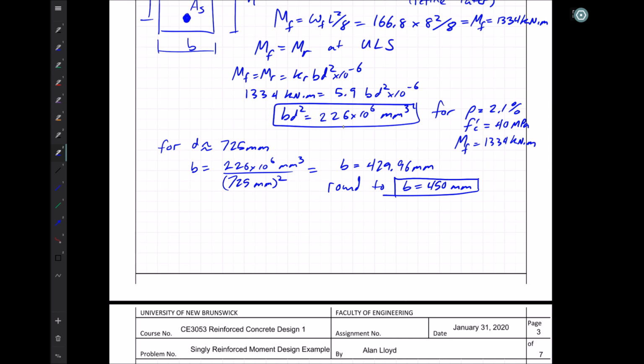Now, as you get into design for reinforced concrete, we're never going to design to a strange dimension. Oftentimes we'll have a lot of limitations around the size of the beams that we can make depending on what company is manufacturing them for us, so who's building it for us. They might have pre-formed formwork or pre-made formwork that they want to use, and this might constrain our sizes as well. We don't want to specify something like 430 millimeters because it's an awkward size to build to. It's an awkward size to measure against and subtract from different measurements for people building it.